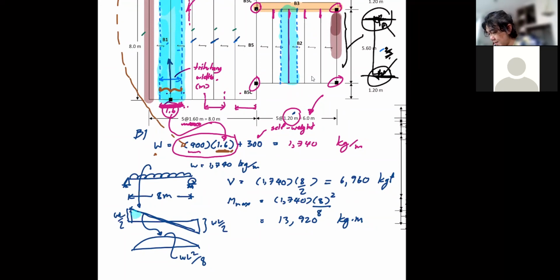That is the shape of your shear force diagram. I'm not going to go through the details anymore, because you should have had this very clearly from mechanics of materials. You have the constant load, so it produces the linear shear. When your shear is linear, it becomes the second degree curve for your bending moment. So your bending moment diagram is going to be like this. This area is positive because you have the positive area from the shear, and then this area will be coming down because you have the negative area from your shear.